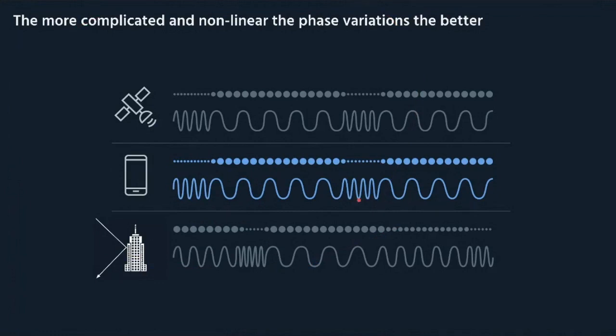We use the inertial sensors in the phone, we use advanced clock modeling, we combine data across different satellites at once in a single estimator of the clock error in order to determine this exact pattern of complicated behavior. We predict what that pattern should be, and we use it to build a unique supercorrelator for this moment in time. We actually build a new supercorrelator every second. Each time it is different to the one in the textbooks.